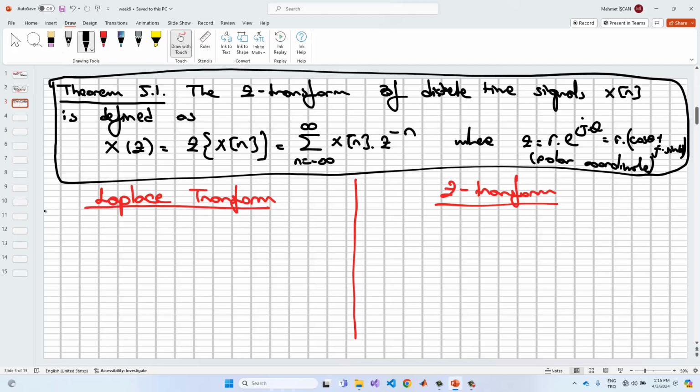First of all, we have F(s) = integral from 0 to infinity of f(t) e^(-st) dt as the formula, and this is the area, and s is defined as sigma plus j omega, right? J omega is only related to the frequency components, but this sigma value is related to the real part, which means this is the real root for this equation, and then we can grow or decay our signal f(t) based on this information. Okay, we can analyze it based on this.